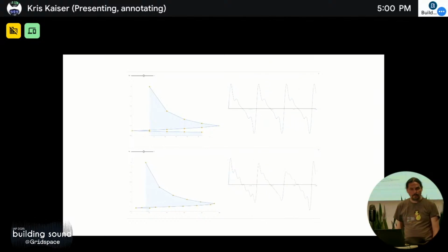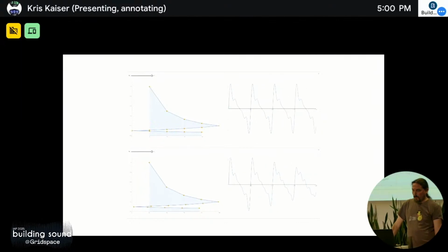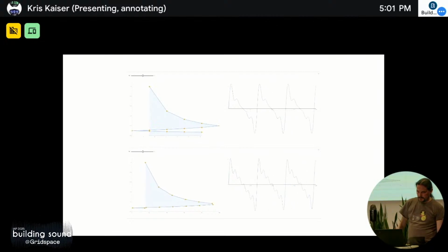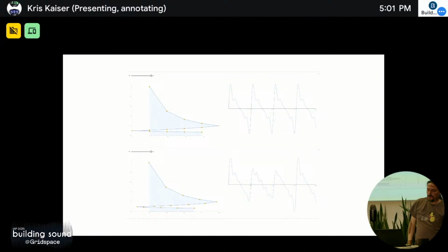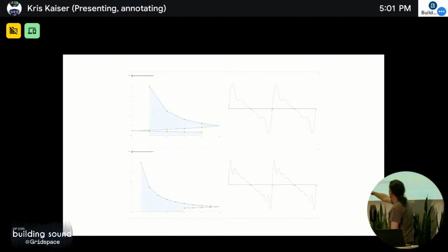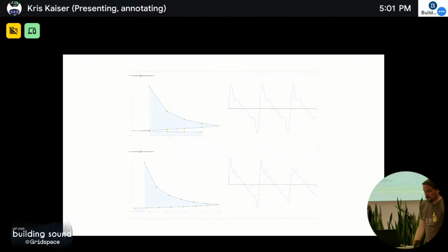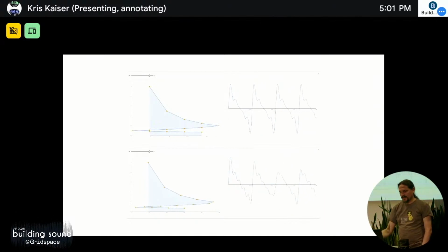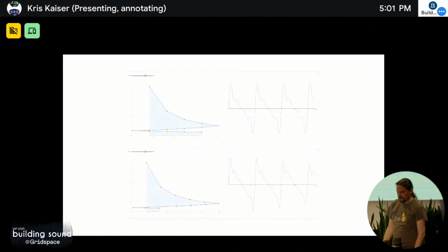So the difference here is just that the Nyquist frequency is set such that the harmonics are aliased. Yeah, in the top graph we're actually changing the sample rate. If you look at the x-axis on the top graph, it's a little hard to see, but it's actually changing along with the pitch. On the bottom we're changing the pitch, but the sample rate stays the same. In the top graph, we're always picking the Nyquist frequency to be 5 times the pitch, just arbitrarily for the sake of the graph.